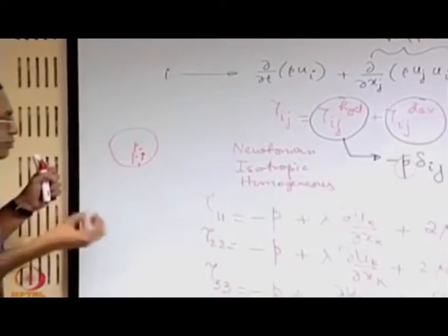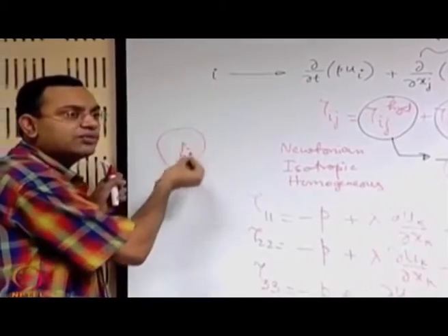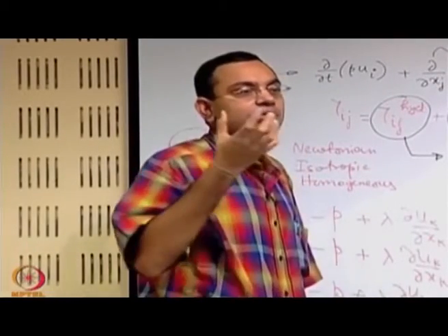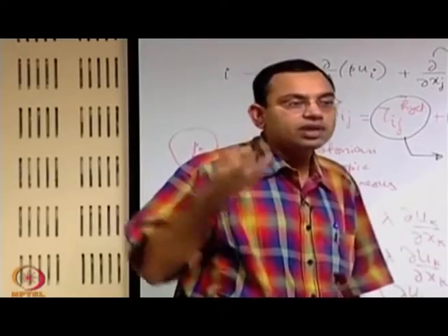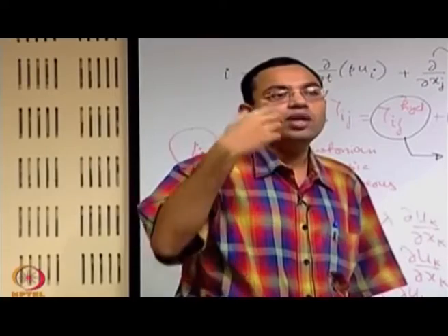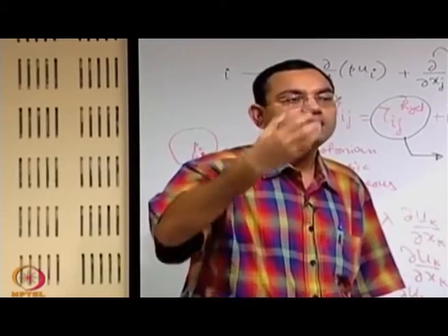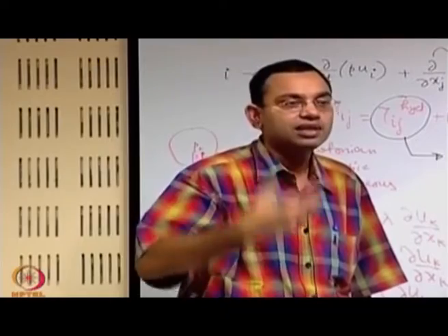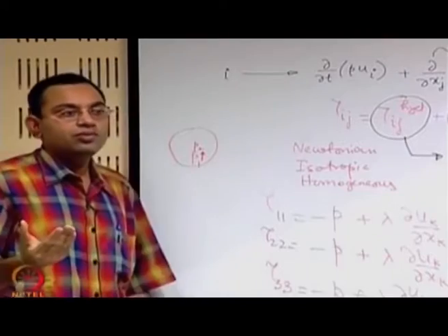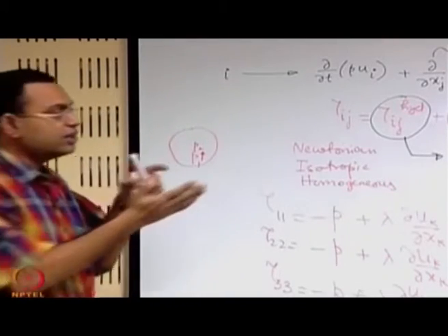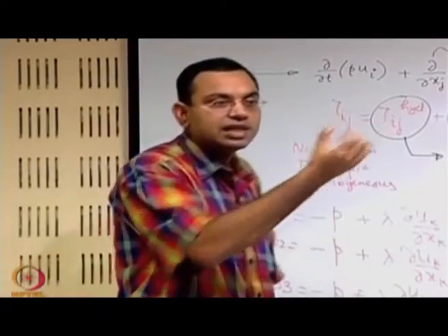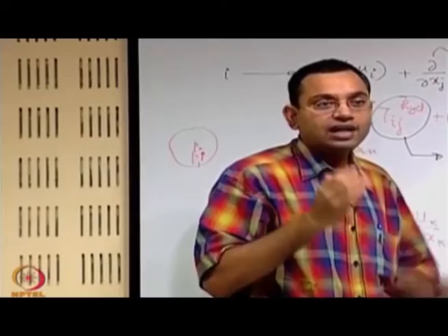That means the sudden change in pressure because of a change in thermodynamic state will give rise to a change in vibrational mode of energy, change in rotational mode of energy, everything, and eventually all these changes in equilibrium will be manifested in the form of a change in translational mode of energy, solely manifested by mechanical pressure. So you should allow a time over which there is a conversion of all those modes of energy into the translational mode of energy that is captured by the mechanical pressure, and that requires a time.